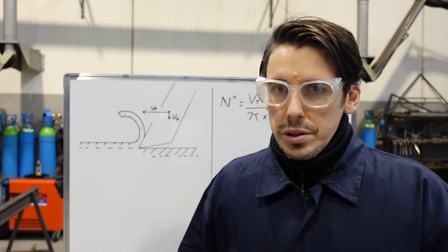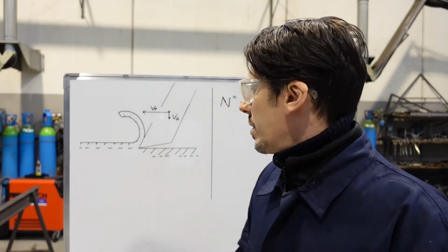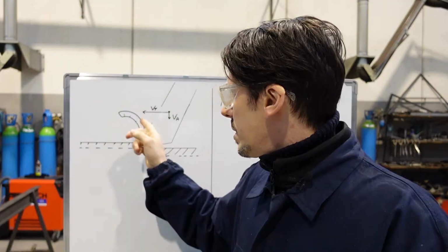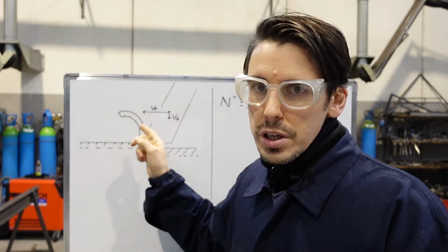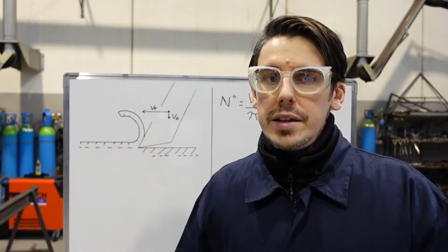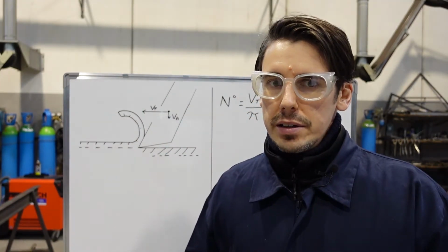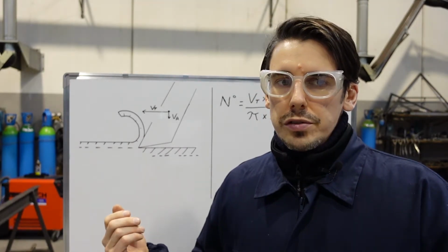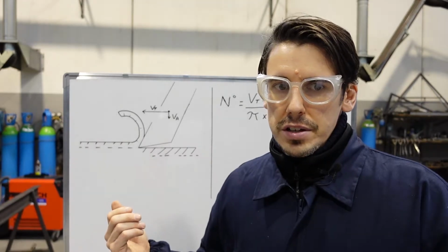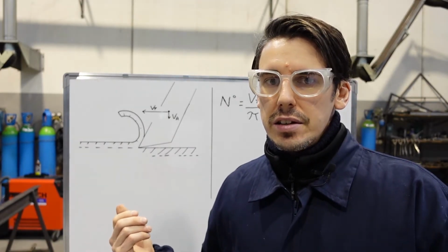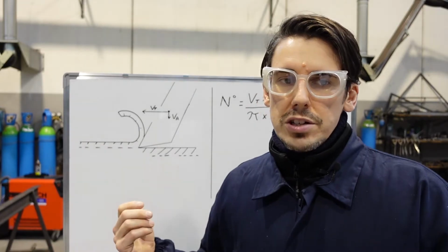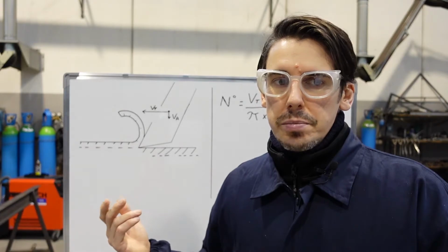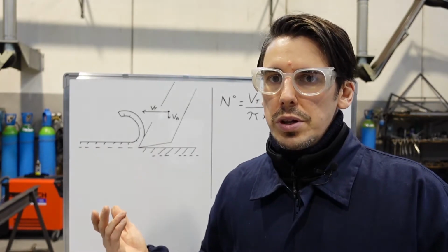This is important to know because if we remove too much chip, or if the chip removed does not go away from the tool, we have more heat. It's important to understand that this speed exists because one of the fundamental points of the processing is to keep the heat generated under control. Too much material moved means excessive friction on the piece and the temperature will rise.